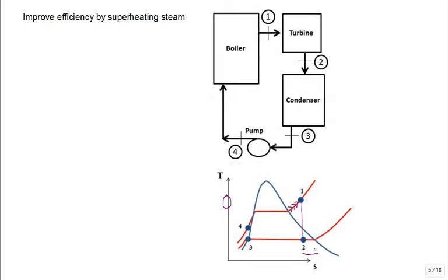One of the things you do is turn it on a side, and the gas is easily turned, and the solids go straight and hit something. So anyway, you don't like that. That's good to get a higher quality at state 2. That's good. So superheat. Good for thermal performance, good for practical steam engines. Okay. So what comes out here no longer is saturated vapor, it's superheated vapor.